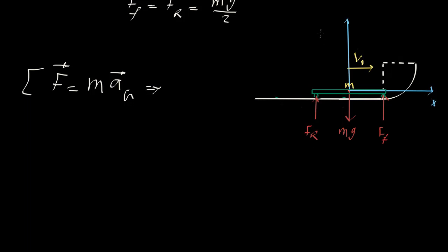So x and y. I can say here that we don't have any forces in the x direction, at least at the beginning. Once the wheel is on the curved path, not at the beginning but over here in the middle, we are going to have the normal surface force in the normal direction to this curved path, and that force will have both vertical and also horizontal components. But once we are here, the reaction of the surface is going to be normal to this path, and here the normal is just in the vertical direction.